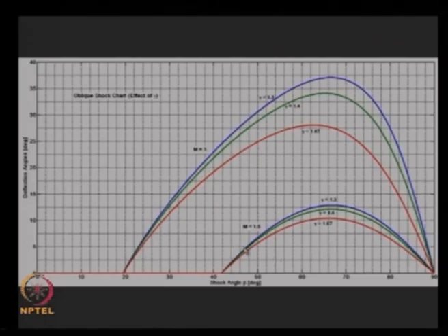Previously it was when it became less compressible, beta increased for weak shock. In strong shock, if I become more compressible, that is I go from higher gamma to lower gamma, I am going to increase my beta, it is going opposite, they have different trends. And one more important thing, the theta critical is higher for more compressible gas. 3 different observations we want to explain.